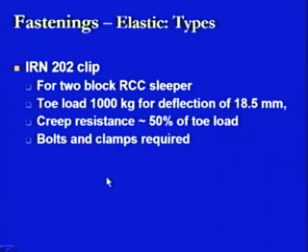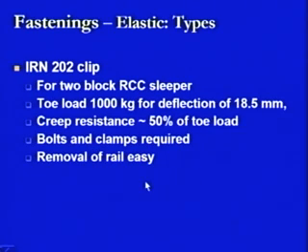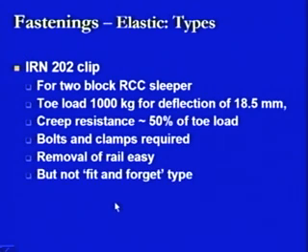To connect this IRN clip 202, we require bolts and clamps, and using these bolts and clamps it can be kept in place. The removal of the rail is easy in this condition, whereas in the case of the pandrol clip it is not that easy. But the problem here is that they are not fit and forget type, whereas the pandrol clips were fit and forget type.